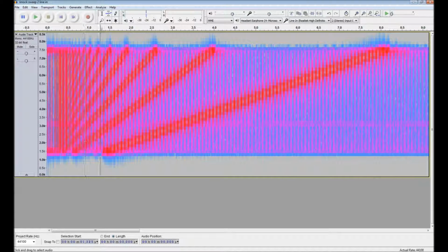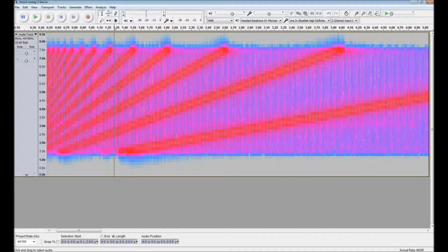The multipliers that I'm speaking of are these frequencies. If you got knock at, say, 6.5, then you also get crap at 3, and it's consistent with the log I showed you previously, that it indicates the main window is from 1400 Hz up to 7.5K.